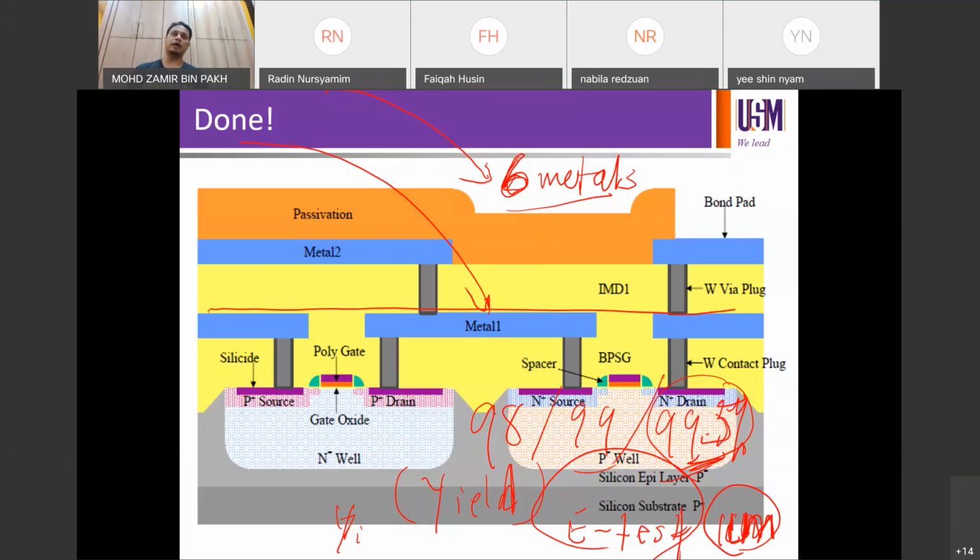So kerja dia check defect for every process step. So if you are an ILM engineer, then you'll probably be assigned as ILM for front end, ILM for back end for a range of different devices. So you can tengoklah all the defects. For example, if you look at the front end of device A, then you're going to be looking at the defects for implantation, the defects for spacer nitride, for polygate, for gate ops, for silicide.